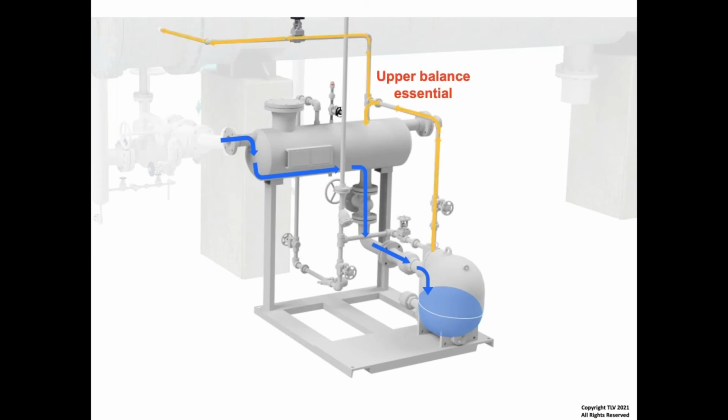In order to do that, we've got to be able to vent out the vapors in order for it to flow in like that, and that's done through the proper balancing. That's why it's important to maintain a vapor space in the reservoir so that you can balance from the power trap into the reservoir and then from the reservoir back to the channel head tapping. And that condenses the exhaust steam.